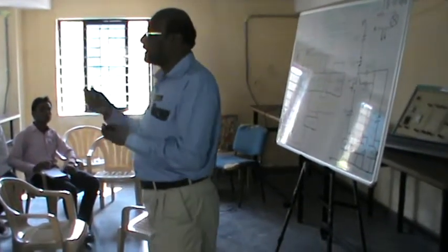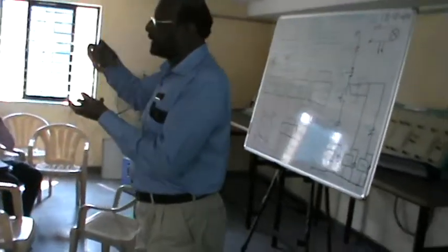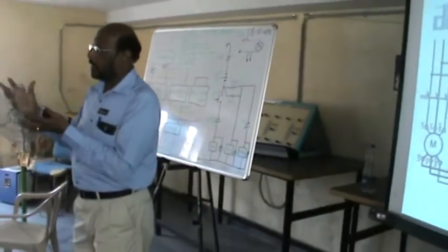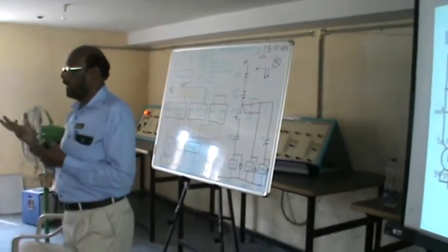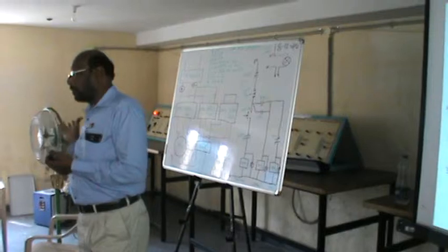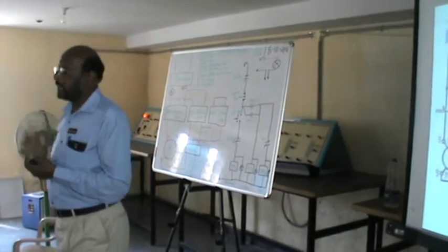Some companies give it on the side, some companies give it on the top of the contactor. So accordingly you have to select. The only thing is you should know how to test the NO, NC and coil. And you know how to test the relay, accordingly you have to get the connection.